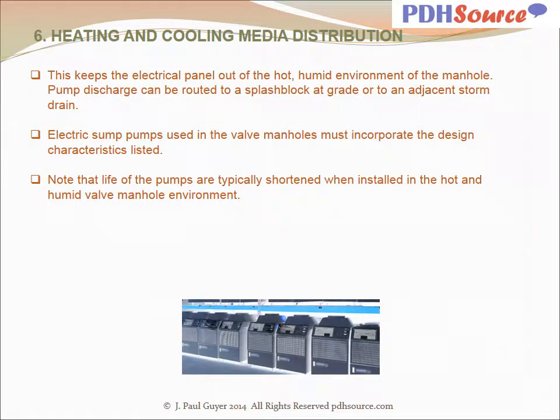This keeps the electrical panel out of the hot, humid environment of the manhole. Pump discharge can be routed to a splash block at grade or to an adjacent storm drain. Electric sump pumps used in the valve manholes must incorporate the design characteristics. Note that life of the pumps is typically shortened when installed in the hot and humid valve manhole environment.